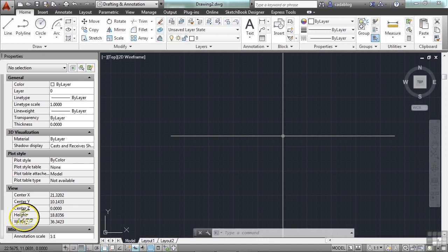Every drawing includes a layer named 0. Layer 0 cannot be deleted or renamed. It has two purposes. One is to ensure that every drawing includes at least one layer. And second, it provides a special layer that relates to controlling colors and blocks. It is recommended by me and other CAD users that you create several new layers with which to organize your drawing, rather than create your entire drawing on layer 0.